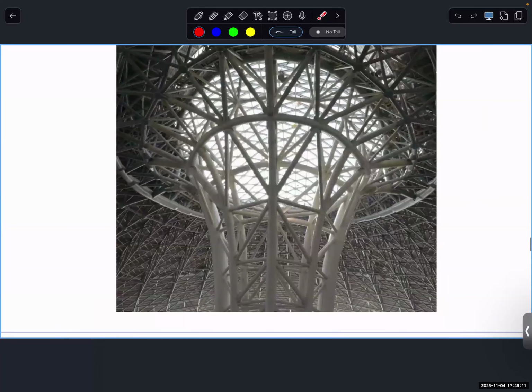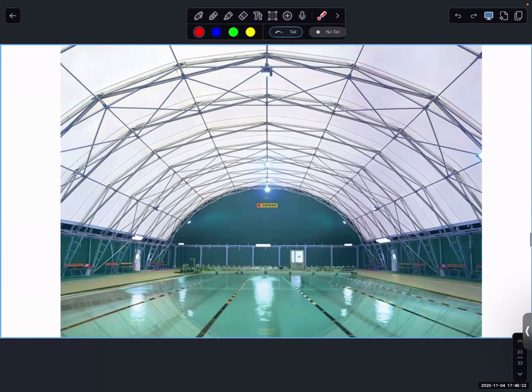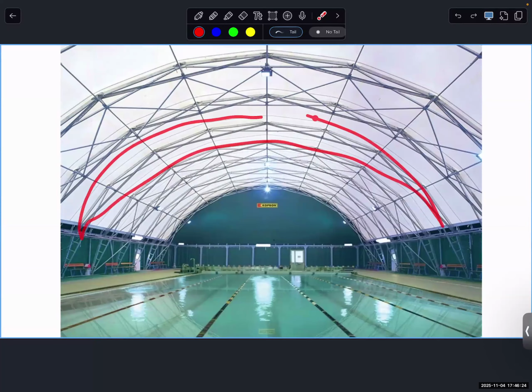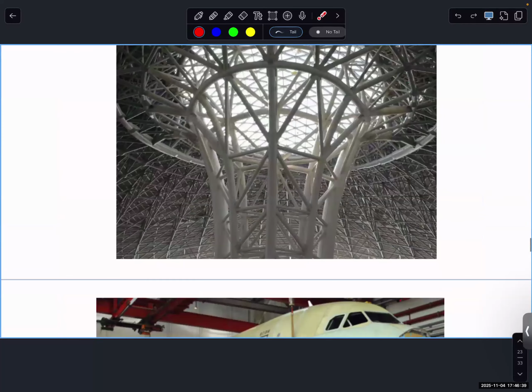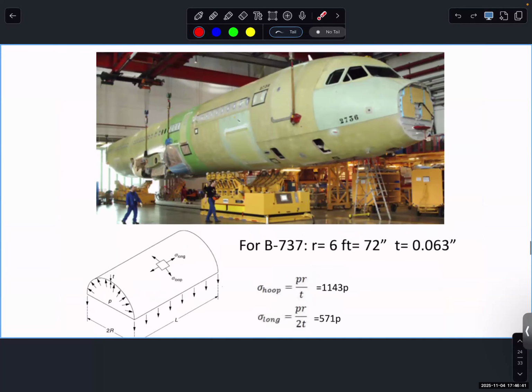You have such a complicated structure. So what do we do? FEA is the finite element method. It discretizes your real structure into small elements. For this one, if you take this section, each one becomes a single bar, and each bar we consider one element. For a complete real-life structure, we assemble them and use software to solve them. It cannot be done by hand calculation. Also, this is a plane stress situation.